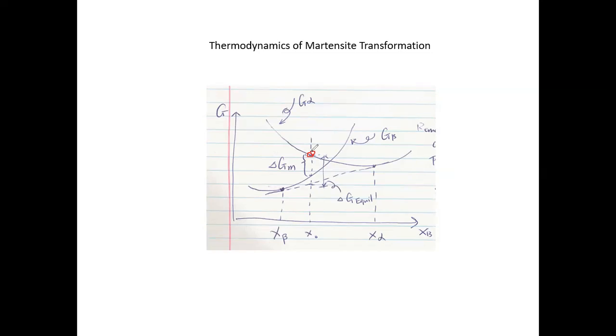So what is the meaning that the system cannot do any diffusion? Well, this means that if you start with a homogeneous solid solution of alpha phase, with uniform solute concentration everywhere, like X naught, then if there's no diffusion, you have to end up with another solid phase with identical uniform distribution of solutes. So this is a consequence of no diffusion. Is it possible for us to have a second solid phase that has exactly the same concentration, and a lower free energy?